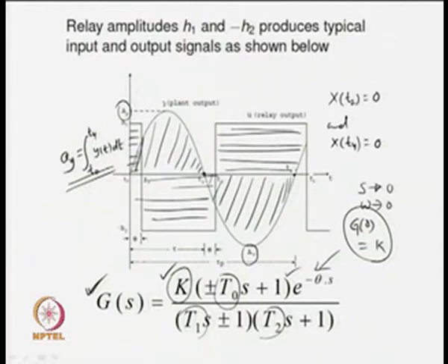So, then we have to make use of this to find the 2 areas, the area for the output signal and the area for the input signal, and next the ratio of the areas will give you the steady state gain. So, K will be equal to Ay upon Au. So, all these things will be developed in sequence.